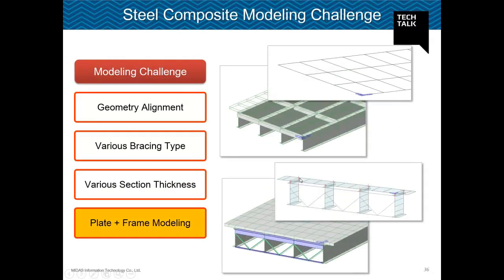For designing the steel girders and deck members separately, one goes for modeling steel as frame and deck as plate elements. The composite action must also be maintained at the same time. This actually would take hours to model accurately to maintain the nodal connectivity between the plate and the frame, or the deck and the girder.